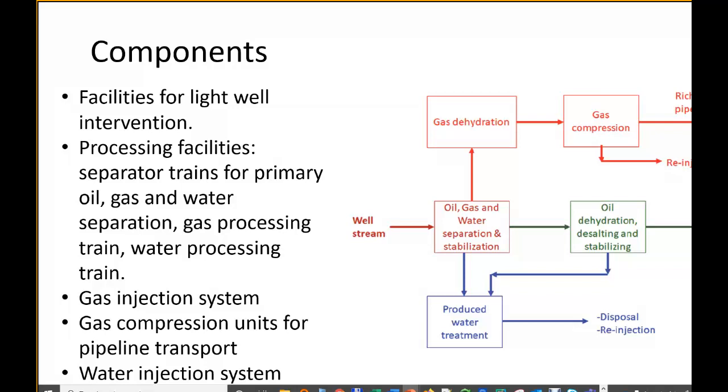Something that almost all offshore structures have in common is processing facilities. Okay? Where we have, if you remember your processing course, oil, water, gas and water separation, physical separation of phases, and stabilization. You want to bring most of the components to the liquid, because that's what pays more. You have hydrocarbon molecules coming out of the reservoir. You want to send most of it to the liquid, okay, because you can sell that at a higher price. And also to separate physically these three phases. You have water, oil and gas, and maybe we should mention here also solids if you have any.